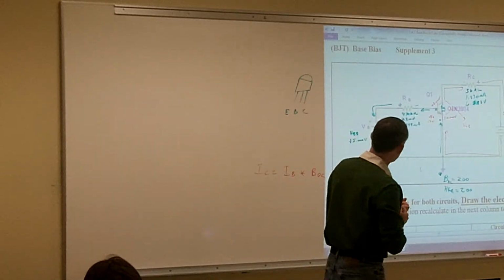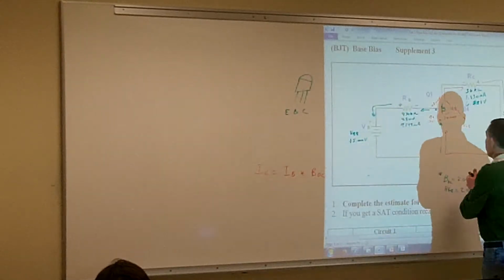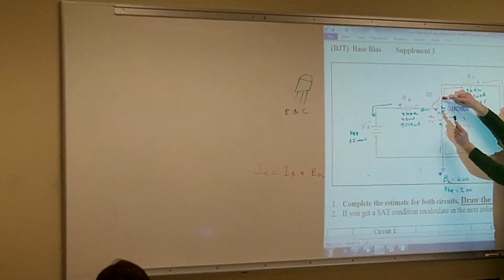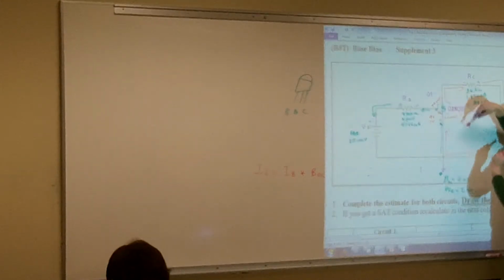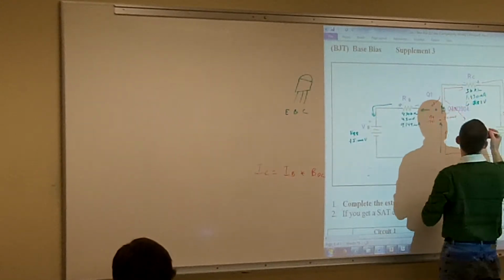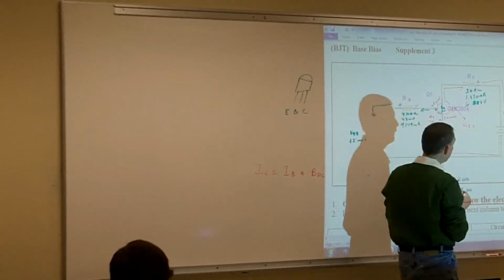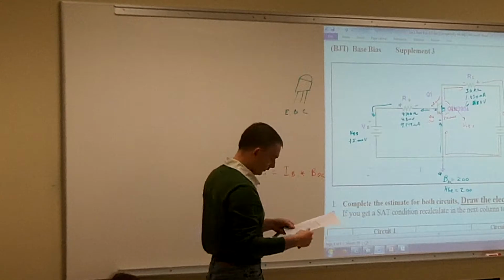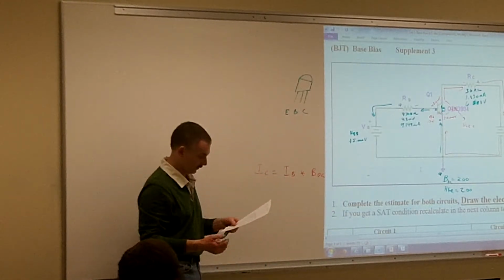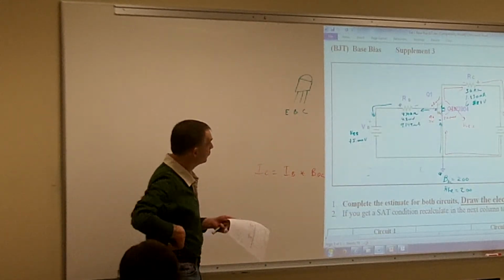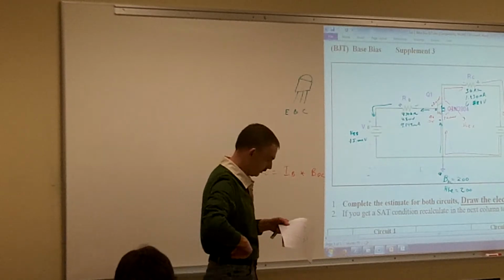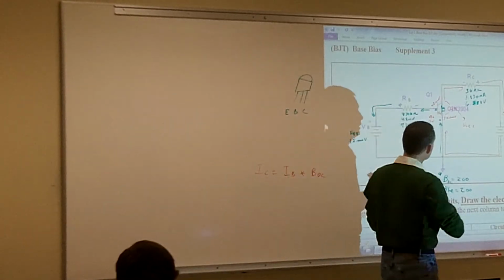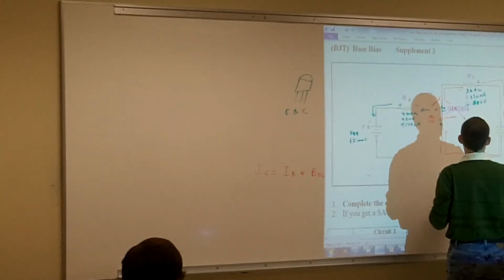And that is a test point, by the way, because we're going from test point C, which is our collector, to test point E, which is our emitter. So it actually does have polarities. So what do we get for our voltage then? 8.412.